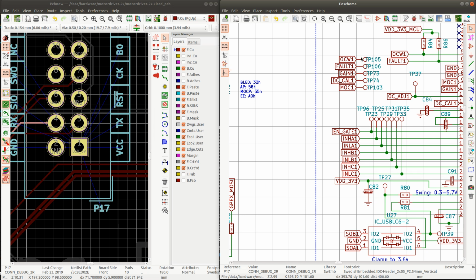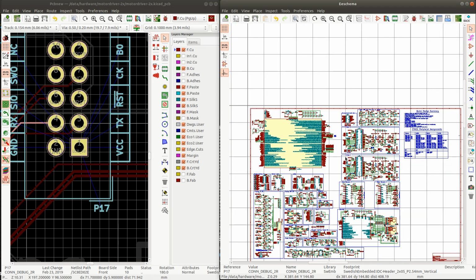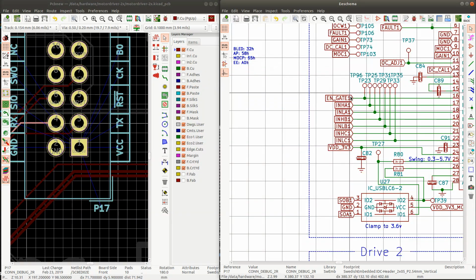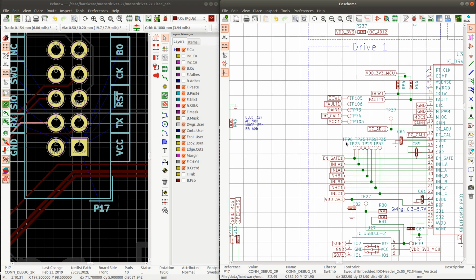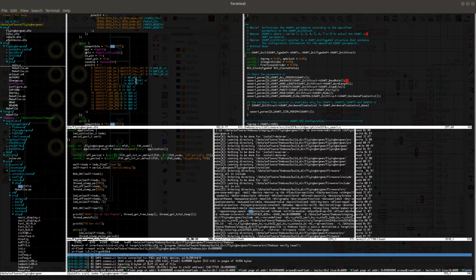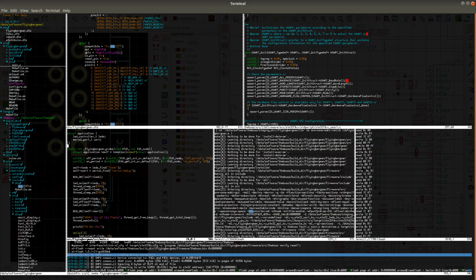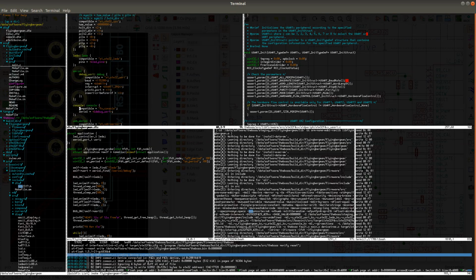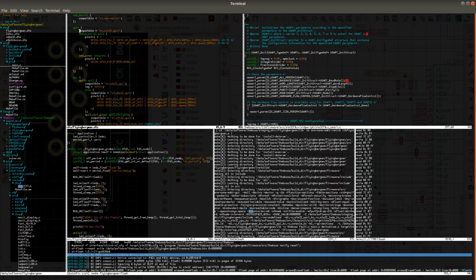What we need to do first of all is just map both drivers in the device tree to the appropriate GPIO pins on the microcontroller. So that's what I'm going to do first. Let's start with driver number 1. In the device tree, I'll define a section which will describe the motor drive chips.